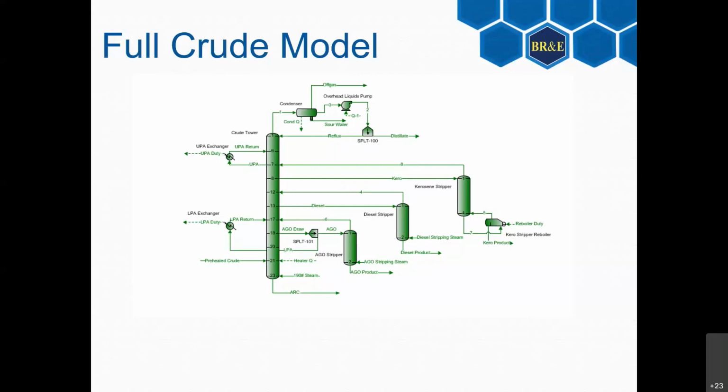So we're going to rise up through the column, and we're going to cool off the column at certain places. We could just have an overhead condenser to provide all the reflux for the column, but we're oftentimes providing cooling at intermediate stages of the column for various reasons, and pulling off intermediate products from side cuts on the column.